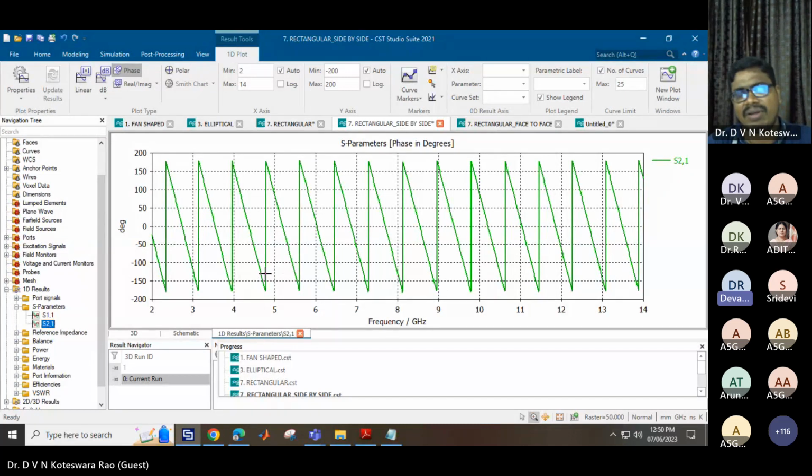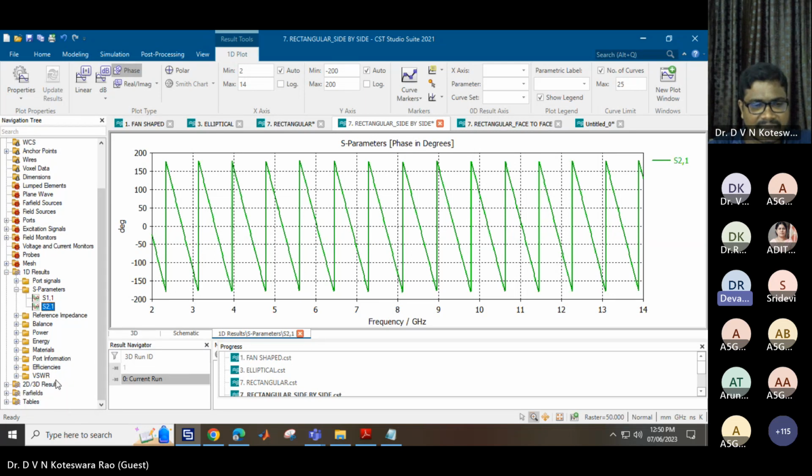If suppose you have designed one ultra wideband antenna with a band notch element, there is some amount of fluctuation that takes place at that particular band notch frequency, which is not to be noticed here because we have designed an ultra wideband antenna. So this represents a linear type of phase response. So S21 value of less than minus 35 dB and group delay variations of less than 1 nanosecond confirm this phase response, which confirms the designed ultra wideband antenna produces a minimum amount of pulse distortion.